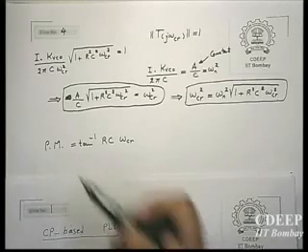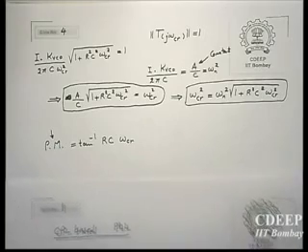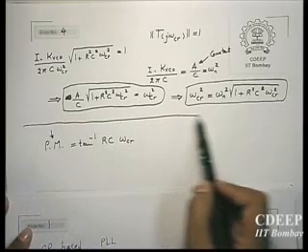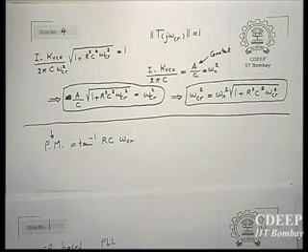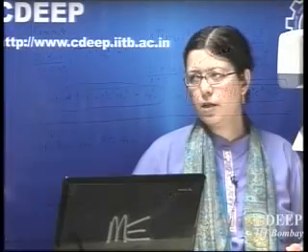But if you go with phase margin, or if you go with Q, which is eventually a similar thing, you will get those two equations and this. So omega CR is your choice. I is determined according to the limitations of power dissipation, and then you decide about Q, therefore you can design. And usually this design is not a one-step design. You will design, you will simulate, and again you will come back and correct your design.